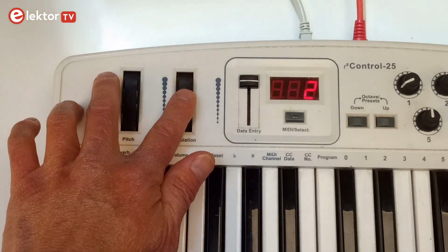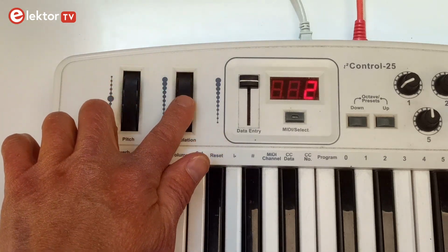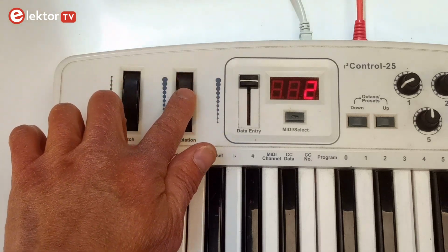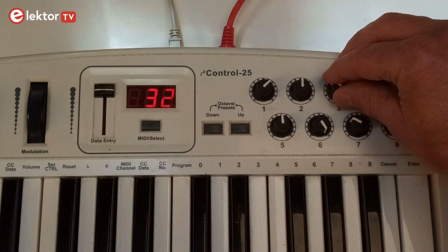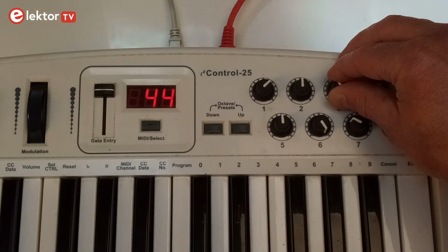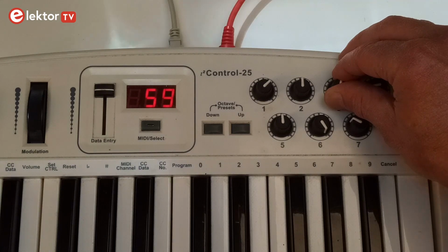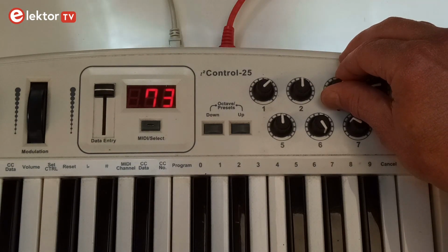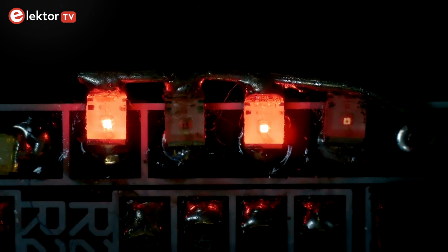Instead, except for the first order low and high pass filters, all other filters have several Q preset values. The 12 dB low pass filter has 3 Q presets. The band pass filter has 5 and the 12 dB high pass filter and the notch filter both have 2 Q presets. This gives a total of 14 filter presets. There is a 15th which is a fixed frequency low pass filter but with a modulated sample rate. The 3 LEDs show which filter variant is active. Their intensity is a measure for the cutoff frequency.